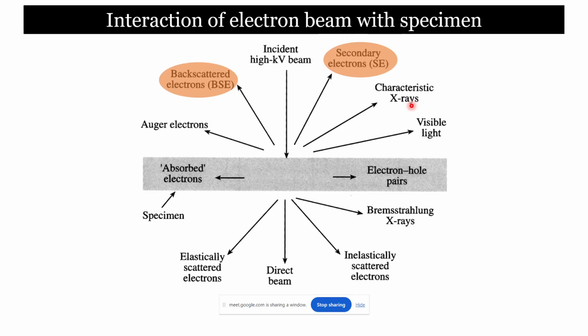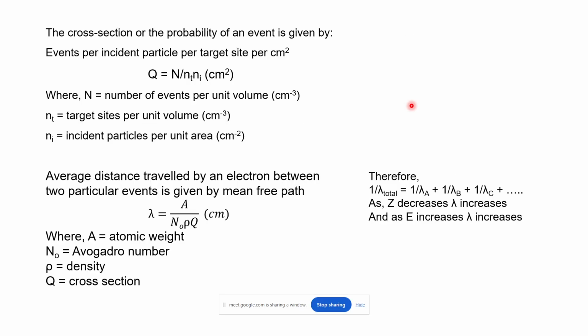So depending upon the element, there are different values of characteristic X-rays emitted from the specimen. Even a single atom has different characteristic X-rays, depending on where the electron is ejected from: the very inner shell, or the outer shell, or the electron is first transmitted from the inner shell to the outer shell and then emitted. So depending on which electron is emitted, you can have different energies for a single atom as well. Today I'll first briefly tell you about